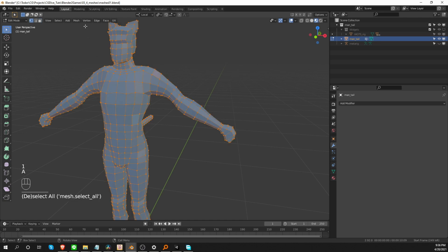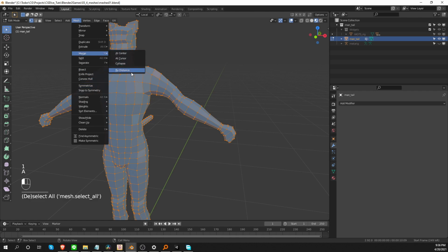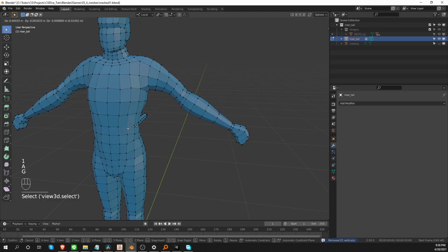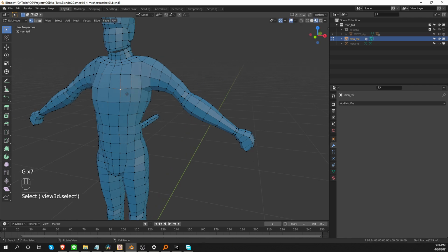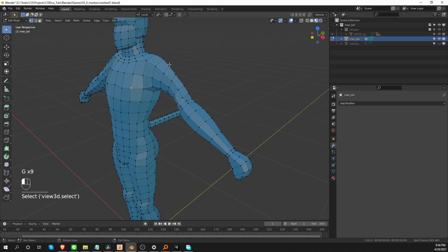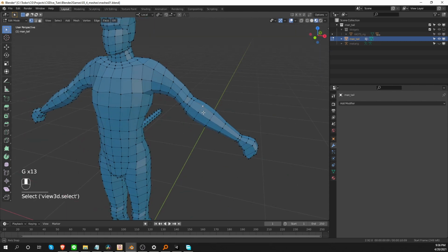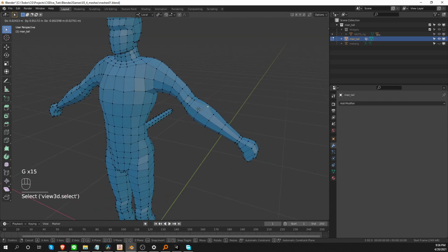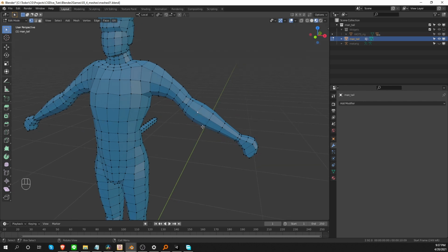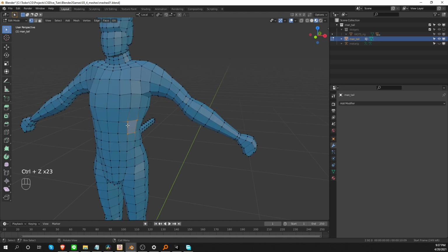So when you have overlapping geometry, one of the easiest ways to fix it is to select all vertices and go to Mesh, Merge by Distance. And that will fix all of these problems. As you can see, this ripped vertex that we had is gone. The cancelled extrusion was fixed, and the cancelled duplication of polygons was also fixed over here. And this geometry that we disconnected was also connected again. So when the bad geometry is simply overlapping with existing good geometry, then doing merge by distance will very often solve the whole problem. But let's undo this until we have our problems back.